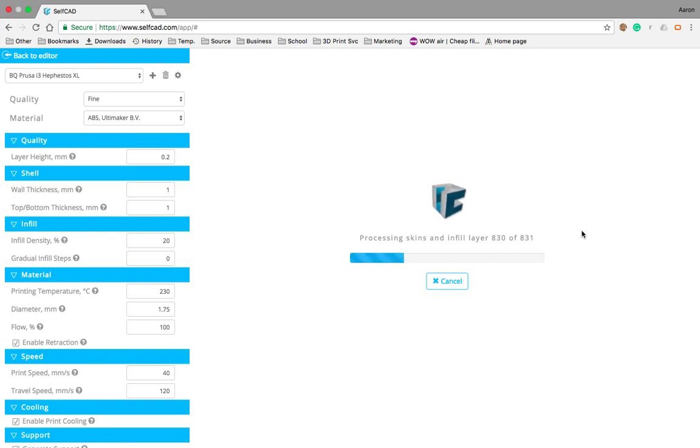So basically the conclusion from all of these tests is, for the first one I've shown you, the basic example, I generally do the magic fix after the Boolean, because you usually have to do magic fix at the end anyway, since even the Boolean may sometimes create geometry that's not 100% printable, like many other features. So I generally do first the image, then the Boolean, and then the magic fix. And I always make it outwards.